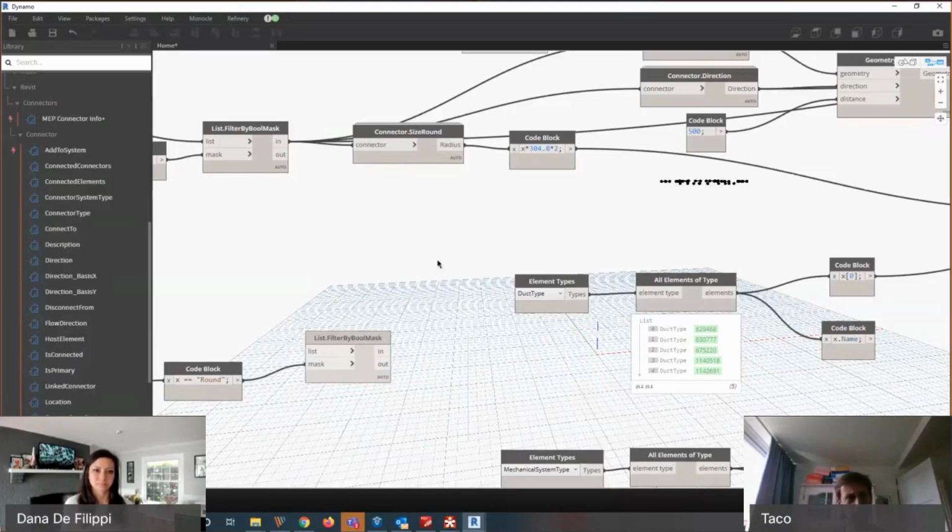Also, there are a lot of questions about propagating information through a network. Revit itself does supply, for ducts for instance, a way to propagate the flow through your entire network. So you get an aggregate or a sum of your entire flow at your air handling unit, where the totals are. But for pipes, it doesn't work that great, or maybe not even at all. So there are quite a lot of questions on whether people can automate that using Revit.